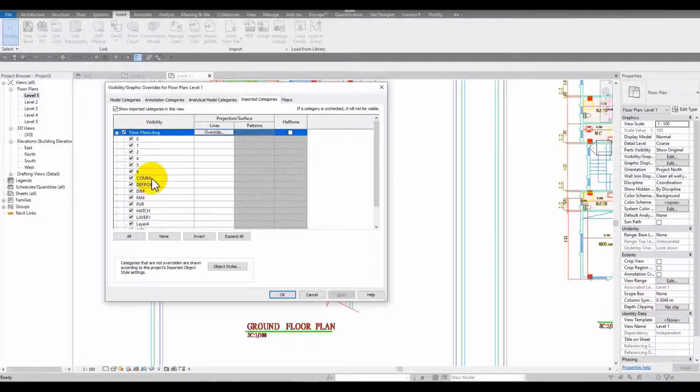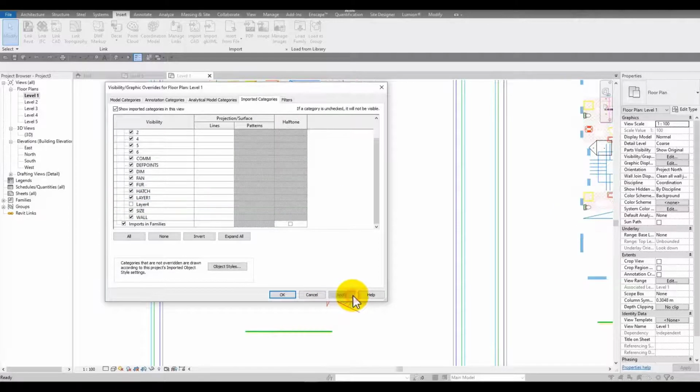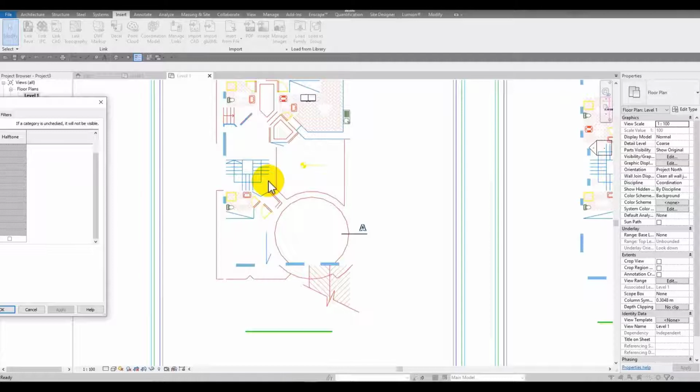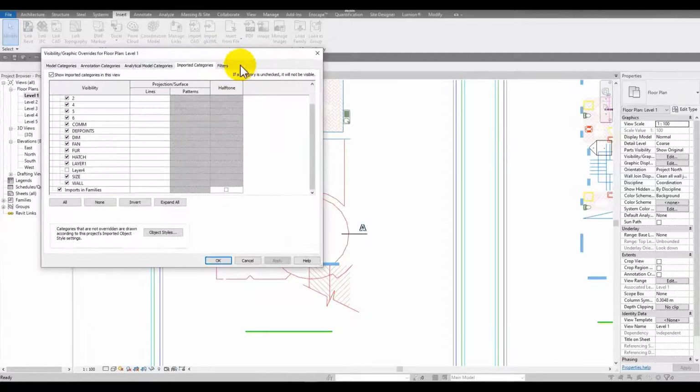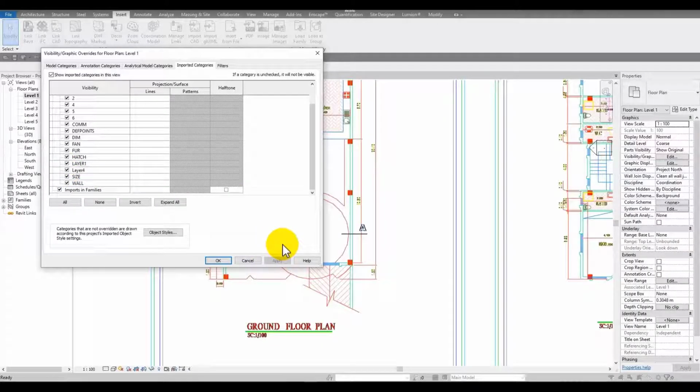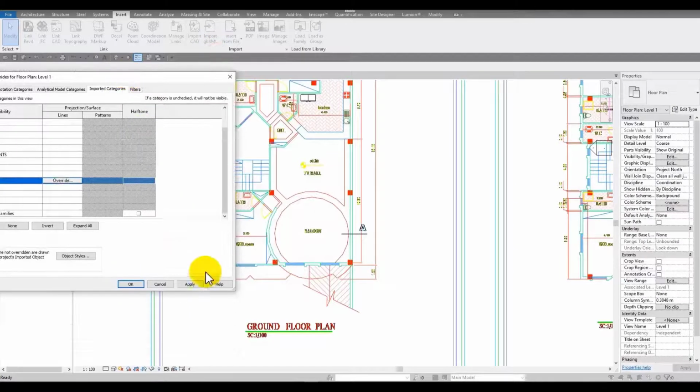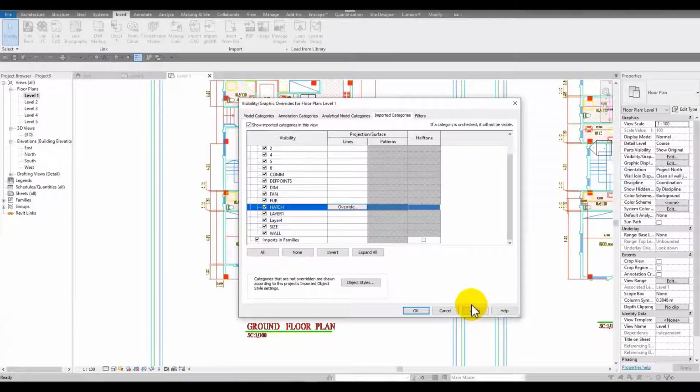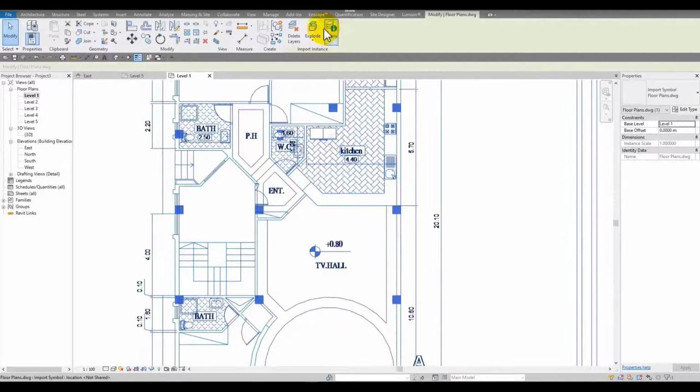When I open it, I can see all layers and I can control them. Layer 4 is here. When I deselect its checkbox and apply, as you can see, the lines will be removed again. They won't be deleted. They will be hidden. When I select it, they will be there again. This time I deselect hatch. If there is anything in this layer, which I think the name of the hatch is something else here,